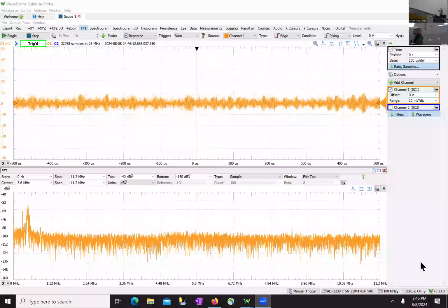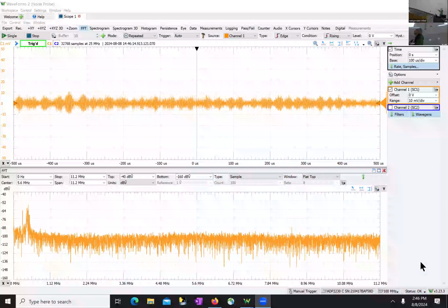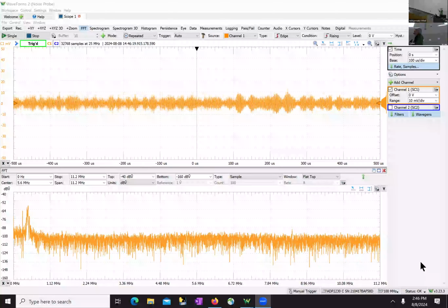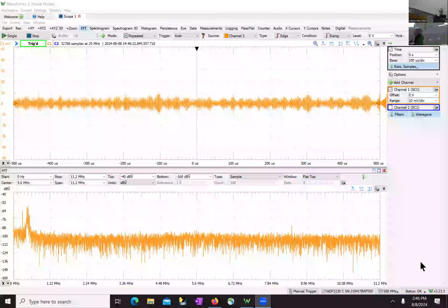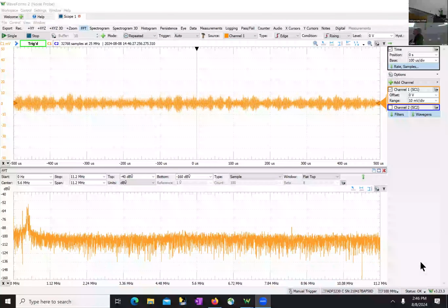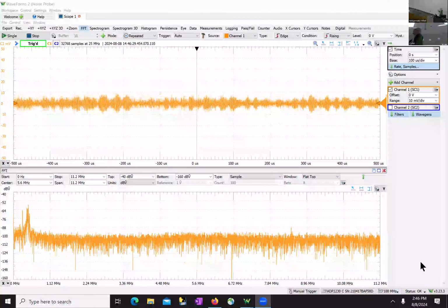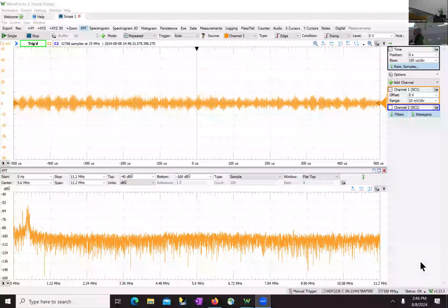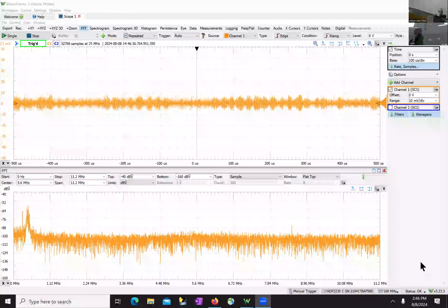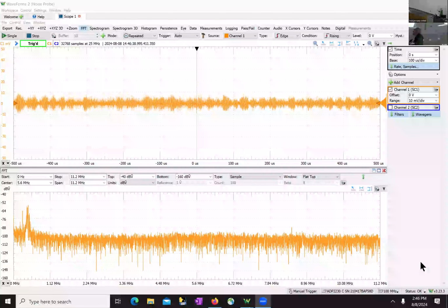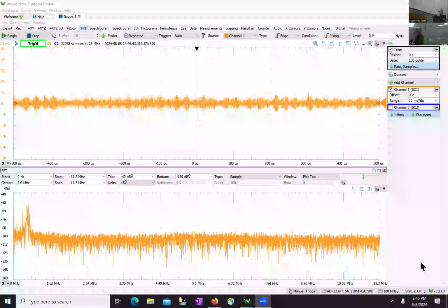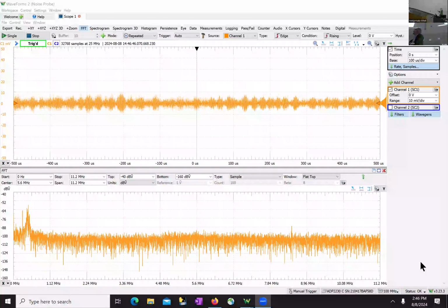But the noise that we talk about, system noise from the nanopore, is an intrinsic noise source, and that has to do with the resistance or conductivity of the wires and the electrodes themselves, plus the resistance of the nanopore. So if your nanopore is 10 megohms, you can calculate the amount of thermal noise from a 10 megohm resistor, and that'll give you a baseline.